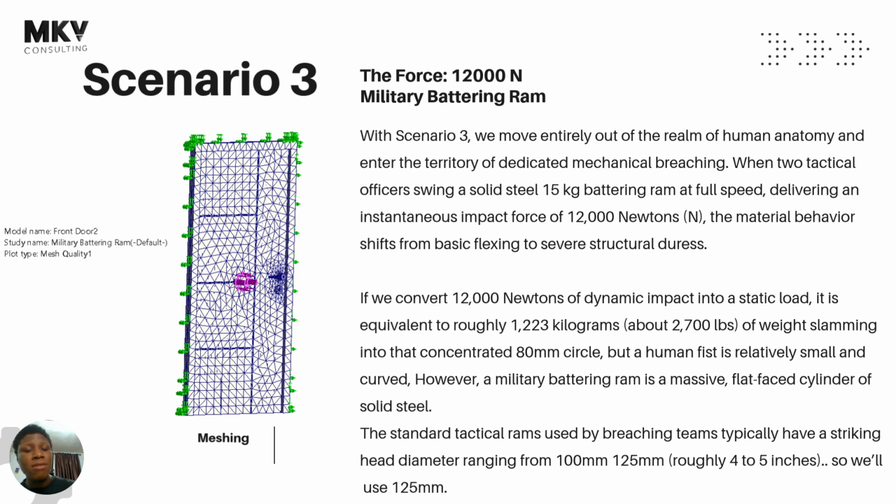For this door simulation, we are not working with hinges, so SolidWorks won't allow the simulated door to slam open. It's not going to simulate tearing; it's going to assume the material expands infinitely, but it will tell you the point at which it actually breaks.